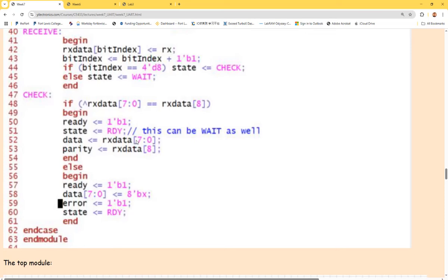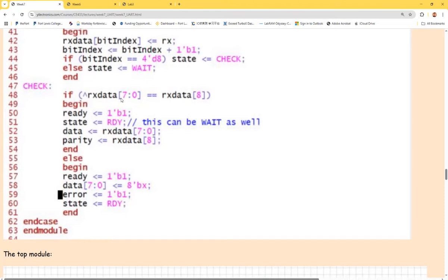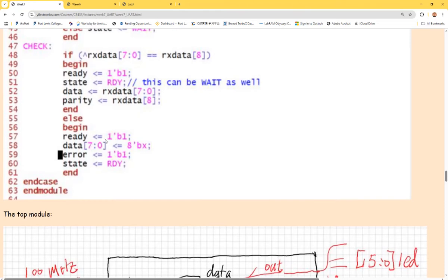So eventually what is being received is 0 to 7, which is the data, and it's generating the parity by itself and placing it at the MSB. So eventually you have 8 bits as the data and 1 at the MSB as a parity bit. All right? And also it's generating an error bit, signaling an error if the parity bit is not the correct one, as a 9th bit. Oh, 10th actually. So eventually you are having data, parity, error.